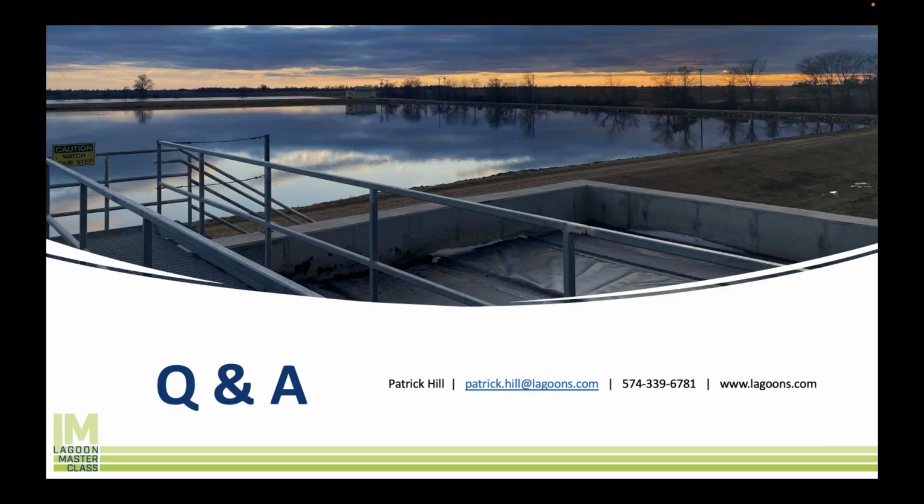And use that as a tool to bide your time to look at the longer term options, and start measuring my sludge, etc. Because overgrowth of algae and duckweed is an indication of an imbalance in the lagoon system, and it's an indication that something's wrong that you need to fix. And you should be addressing those root causes, which are the sludge or your aeration not working properly, etc. In the long run, versus trying to just band-aid the problem as a long-term strategy, which I just don't think is a good strategy.